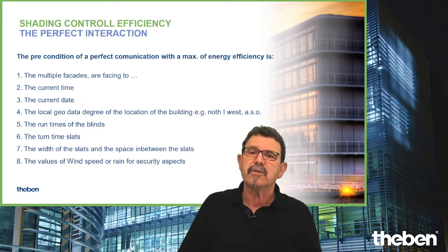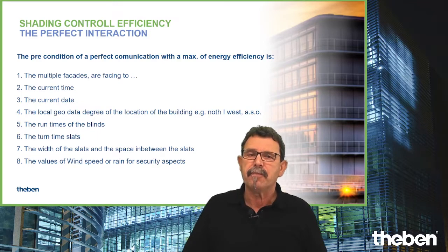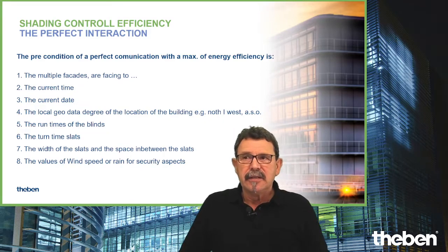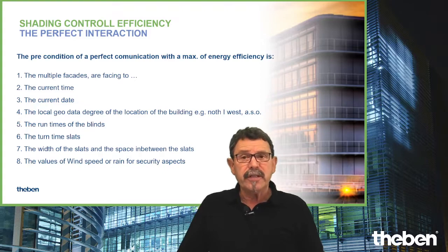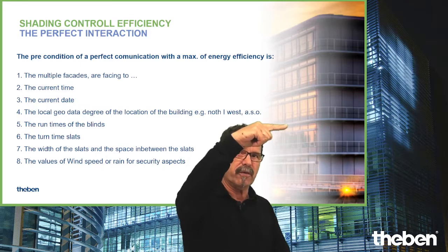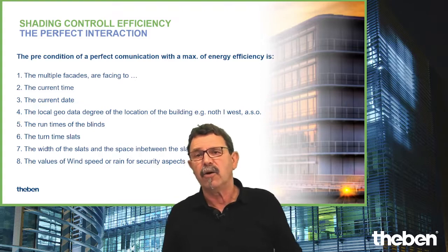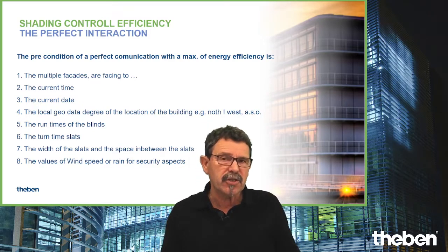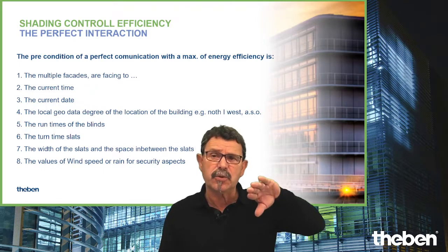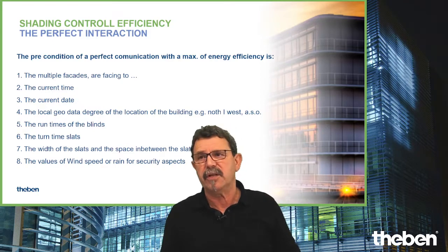So when the sun is rising, what is the positioning and what is the most effect in terms of dazzle? That means we need further details, which are the run times of the blinds. We need to know how long it takes to run down the blinds. It's always related to the dimensions of the blinds. We also need to know the slats turn, so how long it takes to open fully and to close fully the slats.